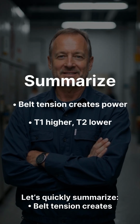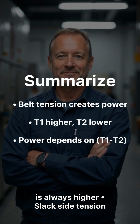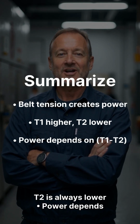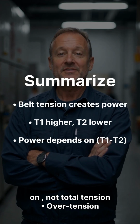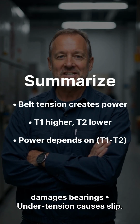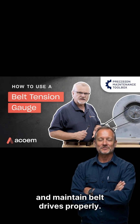Let's quickly summarize. Belt tension creates power transmission. Tight side tension T1 is always higher. Slack side tension T2 is always lower. Power depends on the difference, not total tension. Overtension damages bearings. Undertension causes slip. Understanding this relation helps you design, select, and maintain belt drives properly.